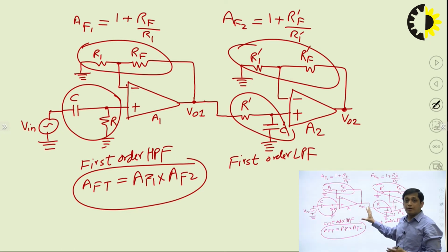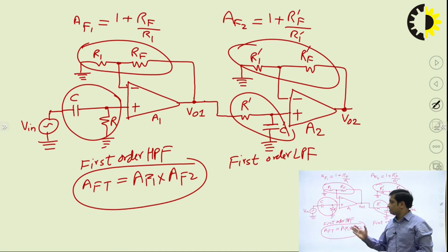And when you build this circuit on the breadboard in your lab, then after drawing the frequency response, you will get FL equal to 200 Hertz approximately. Obviously there will be some error, and FH is equal to 1 kilohertz. Fine. So up to now I have discussed how to find the component values for particular cutoff frequencies for a wide band pass filter. Firstly we have designed the first order high pass, then the first order low pass filter.